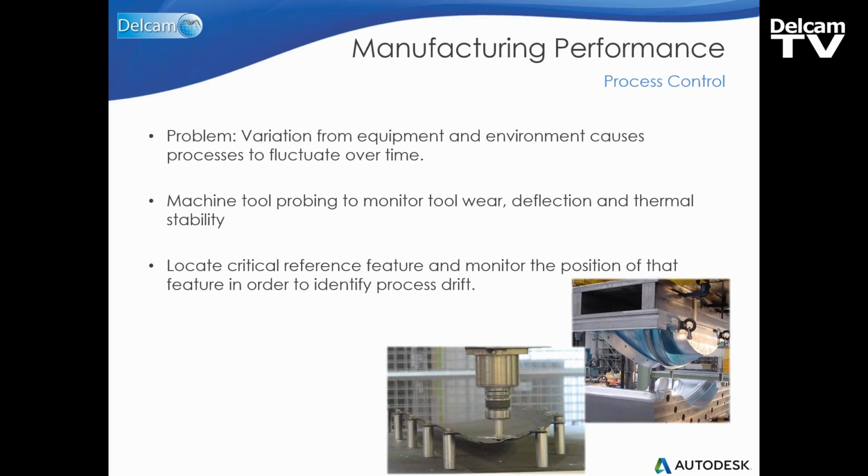So let's just contrast that with how we might have done it otherwise. If we were to inspect post-machining process, then the fluctuation from the tool wear or from the thermal expansion wouldn't perhaps be identified until after we've machined 10 or perhaps even 100 non-conforming parts. And then of course that's a real problem for us as a manufacturer, in that we might even have to scrap the parts, or we'd have to put them back onto the machine for rework.